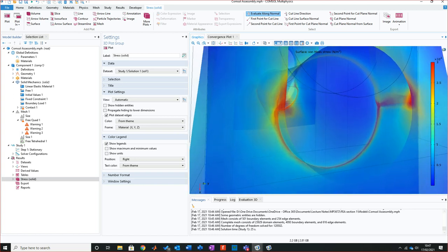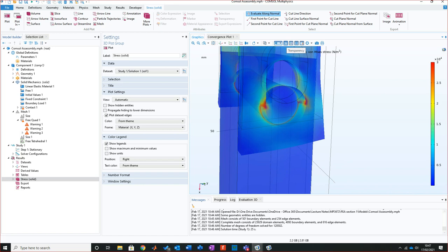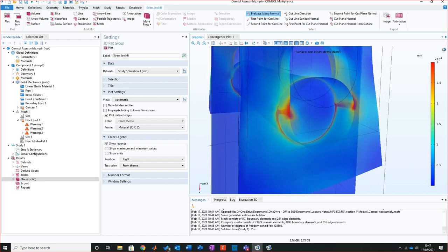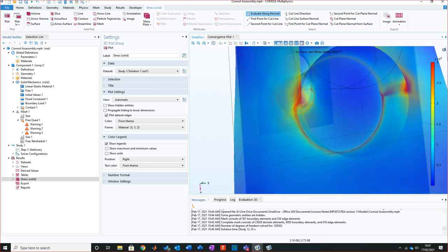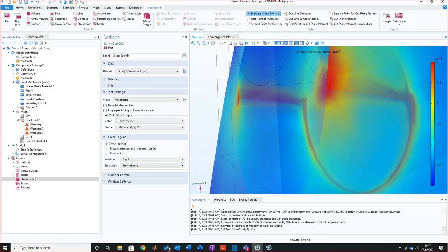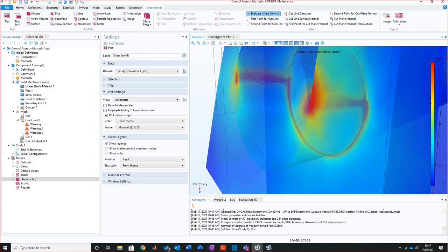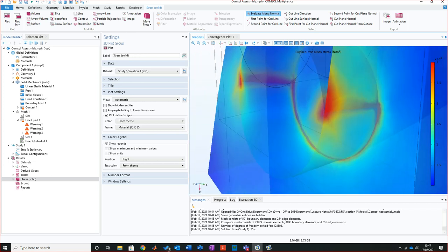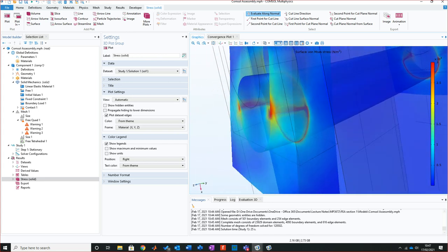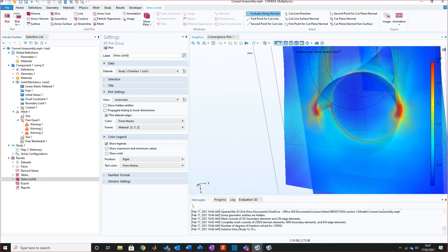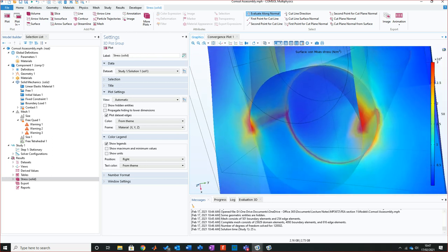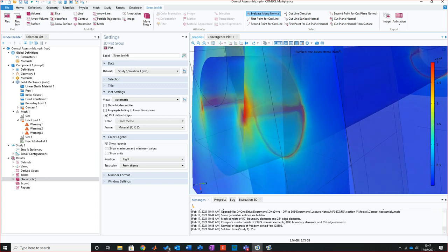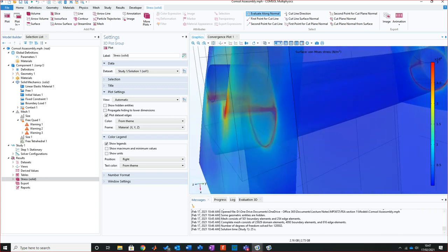What I can start to do, just to show you, is use transparency, by the way. I'm only just operating around transparency, but I can start to see what's happening. Now, see here, this is a little bit irritating. It's something I could fix with the geometry, actually. But you see there, this has happened because it's seen as separate faces. But because that pin itself is an interference fit, you can see there that it's really heightened around that pin interface here.